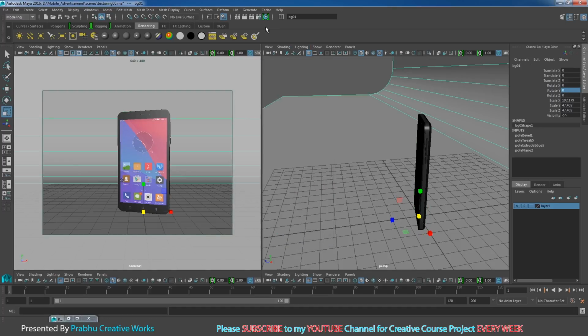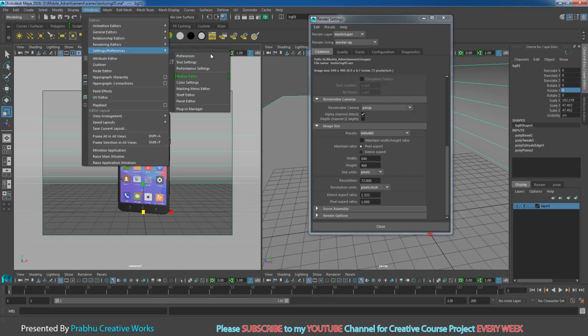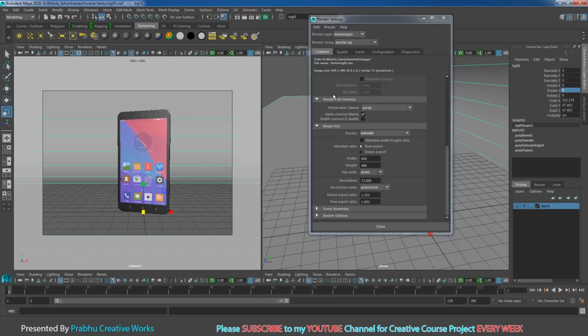Before that, go to render settings. Here you need to choose mental ray. If you don't have this mental ray option in the render using tab, you want to enable it in settings and preferences. Go to window, settings, preferences and choose plugin manager. Scroll down and here you need to choose Maya to MR, load and auto load. Then close. That means now you have this option in render using. So I want to choose mental ray.